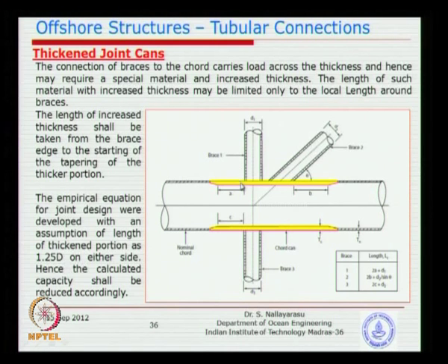So the formula for PA, the formula for MA, those formulas were developed based on the assumption that this length from here to the end, the yellow color, the extended can, is 1.25 times the diameter. That was the assumption they made in the equations. Now, if you provide the minimum as 305 or d by 4, will the capacity be smaller or bigger? It will be definitely smaller. So, there will be a reduction that you have to apply to the calculated value of PA. That is what we are going to see.